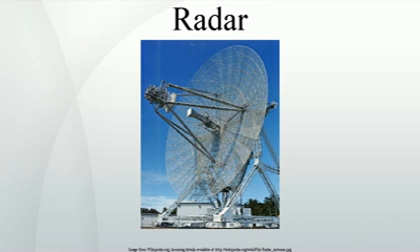Clutter may also originate from multipath echoes from valid targets caused by ground reflection, atmospheric ducting or ionospheric reflection-refraction, for example, anomalous propagation. This clutter type is especially bothersome since it appears to move and behave like other normal, point, targets of interest. In a typical scenario, an aircraft echo is reflected from the ground below, appearing to the receiver as an identical target below the correct one.